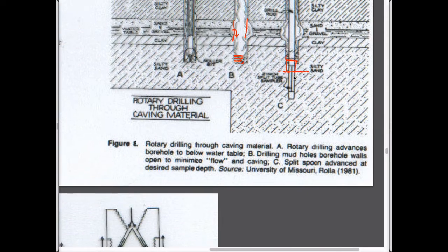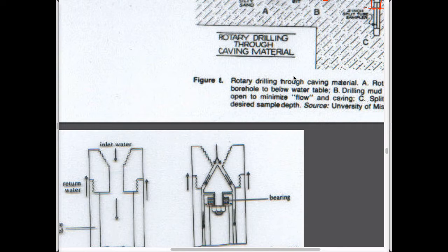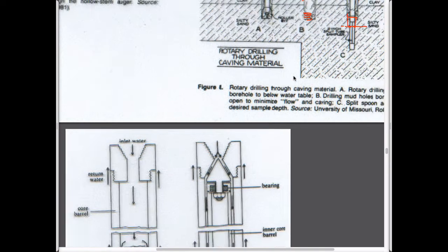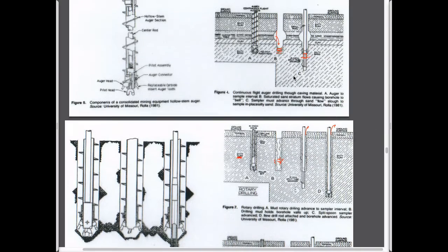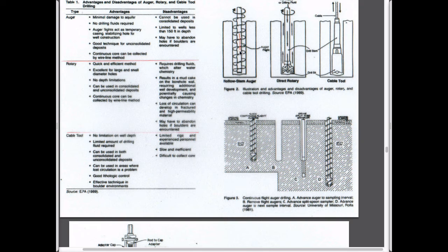And so those are the methods that end up being used for drilling. Well, I guess I've gone past them, right? I've zoomed in on this so much that it's made it not so obvious. Okay. So remember, end members. Augering for soil, rotary drilling for rock and soil, diamond drilling for rock only. You don't get a sample with this without pulling the drill string, but there are hybrid methods of these.